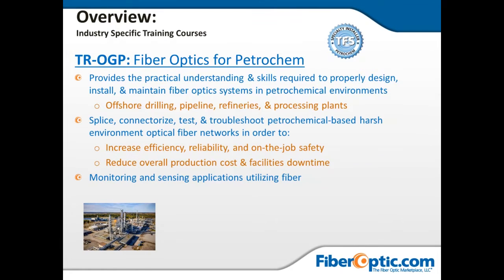We also get into monitoring and sensing applications in this class using fiber. That means many times the fiber is used for sensing: temperature, vibration, pressure, that may need to monitor pipelines over long distance in a shifting geology or geographical type of environment.